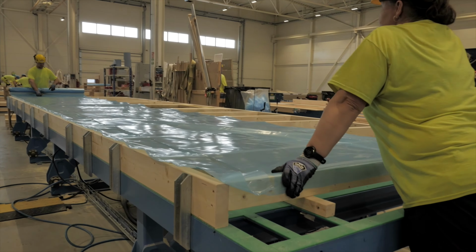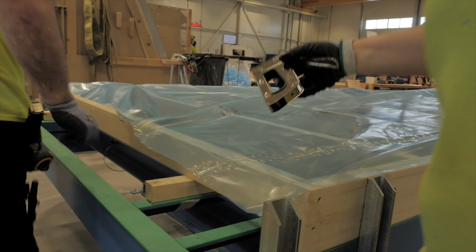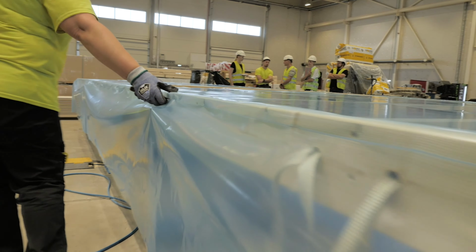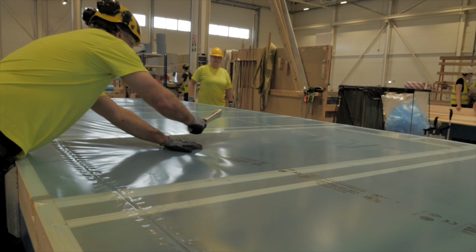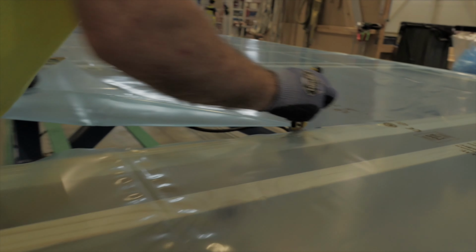In the following case, the vapor barrier is first secured with staples on the edges of the frame. To secure the barrier tightly, the vapor barrier film must be overhanging both at the edges of the panel openings and at the periphery of the perimeter. If there is a need to continue the film, then the film panes must be installed with an overlap and the continuation points must be sealed with tape. Bear in mind that it is not allowed to install a vapor barrier film in the walls of damp rooms on which waterproofing is provided.